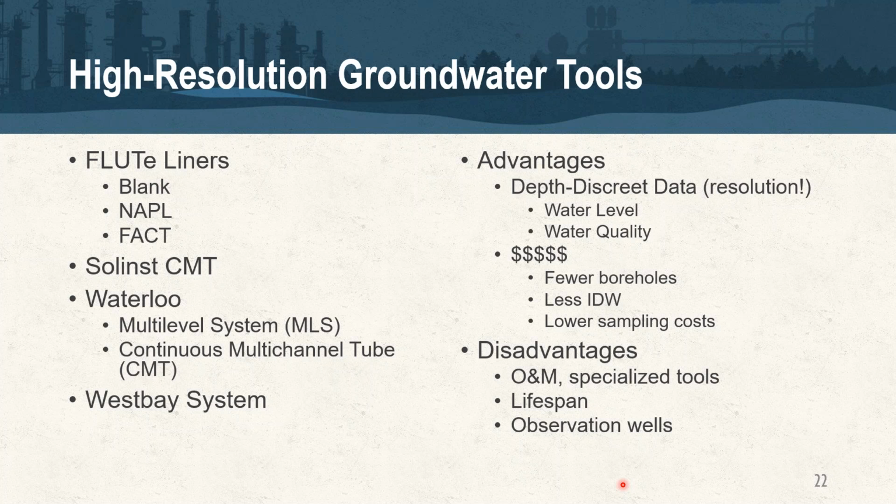But these have advantages and disadvantages like every tool. The biggest advantage is these provide depth discrete data, extended time periods to evaluate that same feature, fracture, interval. They can be, depending on the deployment, inexpensive or expensive. Again, a tool is a tool. But the idea is to decrease the amount of boreholes you have on the site, especially if you're reusing these, you're pulling them in, pulling them out during injections or post-injections, replacing them.